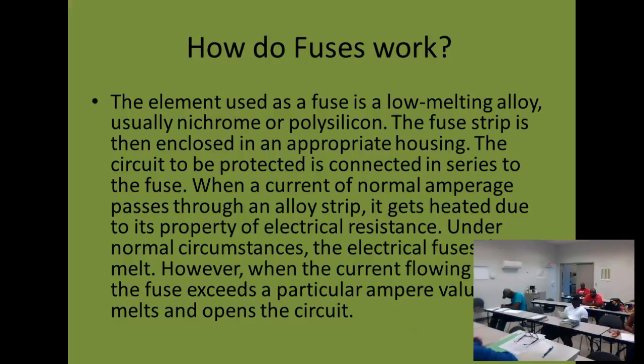What else do we need to be clear about? Okay, these meters, and I'm going to catch you in here working in the lab, you're going to make a mistake. They're made to be used to take voltage in 2 places. Across the source of power. That doesn't mean I have to be right at the power. Power has wire. Maybe it left from there and it's here now. But I got to be across the source.